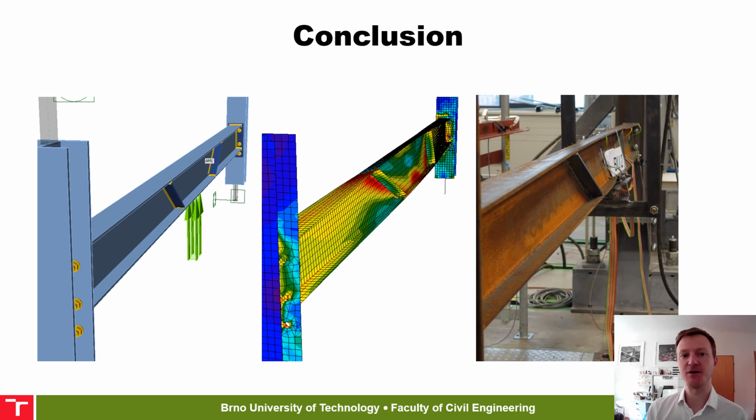The model was verified on several examples using hand calculations for cases with clear boundary conditions, our experiments or experiments from the literature. We also cooperate with ETH University in Zurich on verification studies, and it seems even members of class 4 can be safely designed by CBFEM. Using the imperfection provided in Eurocode always provides the safe estimation of the load resistance. The CBFEM model is automatically generated, so it does not require deep knowledge about finite element analysis. The software is free to all students and educators.